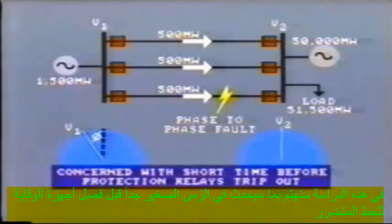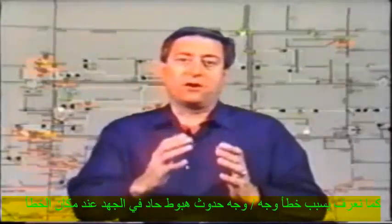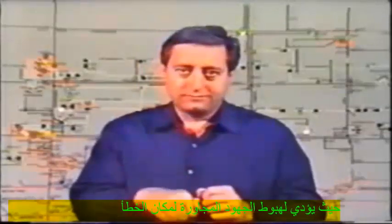In this study, we are concerned with what happens in the very short time frame before the protection relays trip out the faulty line. As we know, a phase-to-phase fault will cause the voltage to fall to a very low level at the location of the fault. This will cause voltages in the vicinity of the fault to fall.